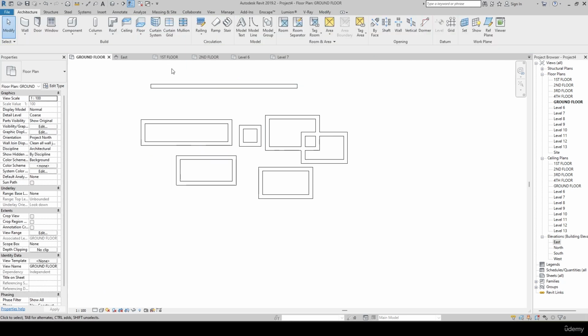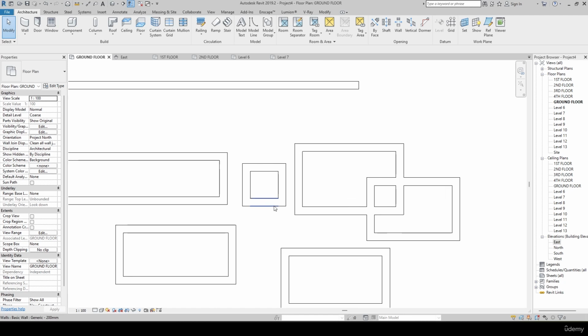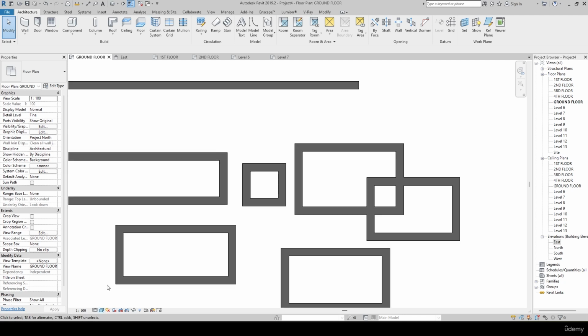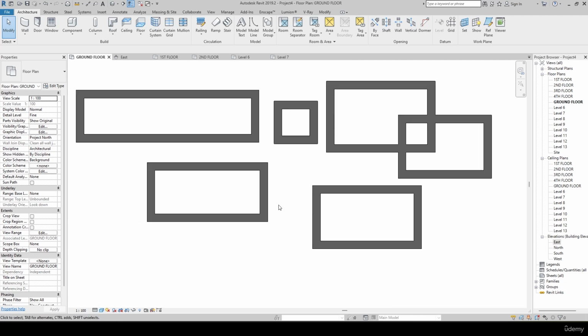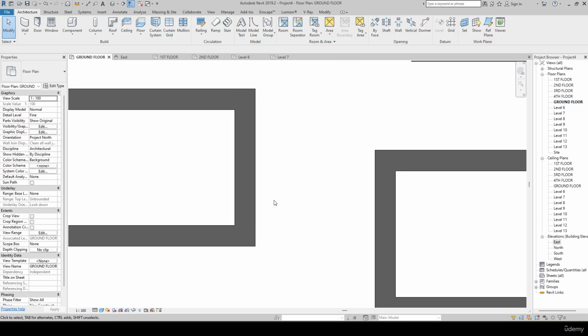These are the different location lines in the walls, right? In order to view the walls in detail, as I told you earlier, you have this section. We call it the view or the detail level. As of now, I'll select the detail as coarse, I can select medium, or I can select fine, and for the view I can select shaded. So you will find this in the shaded design. As of now the wall has been selected as only the basic wall. That is the reason there are no properties showing.